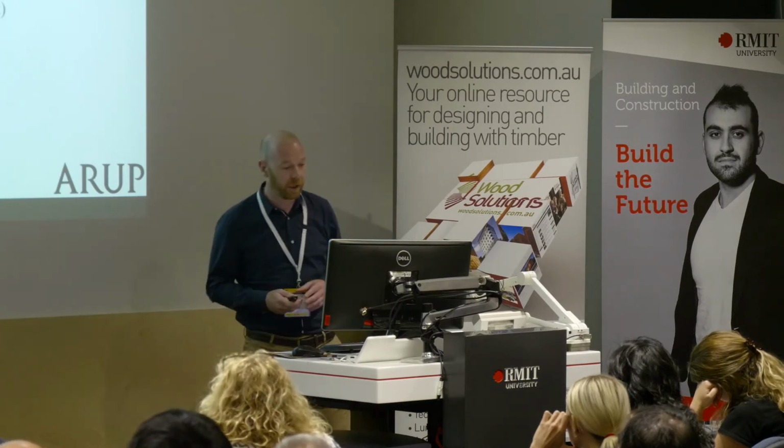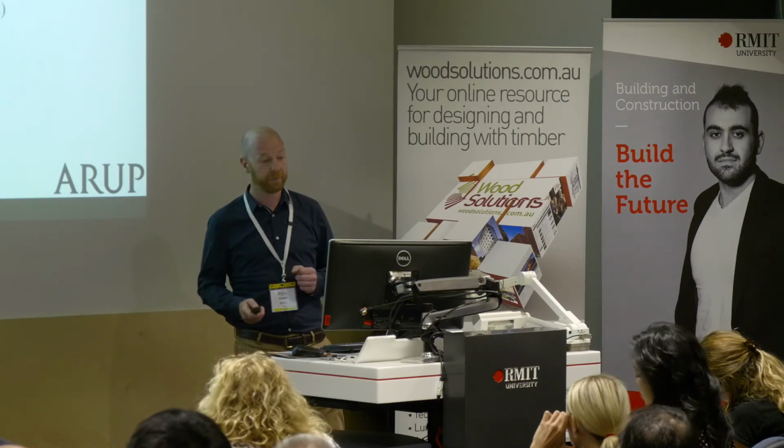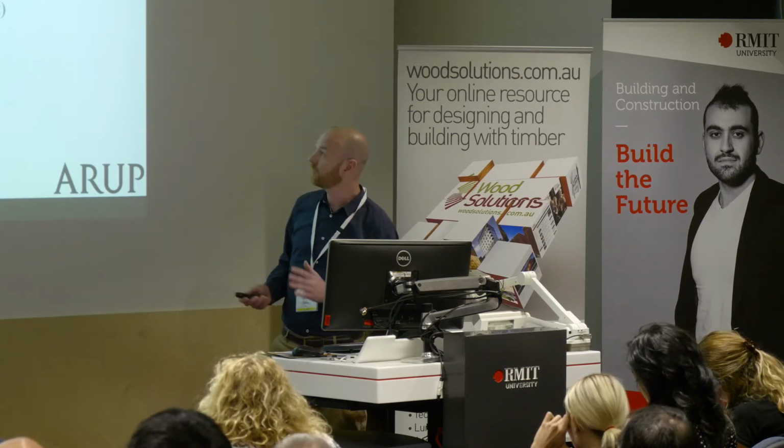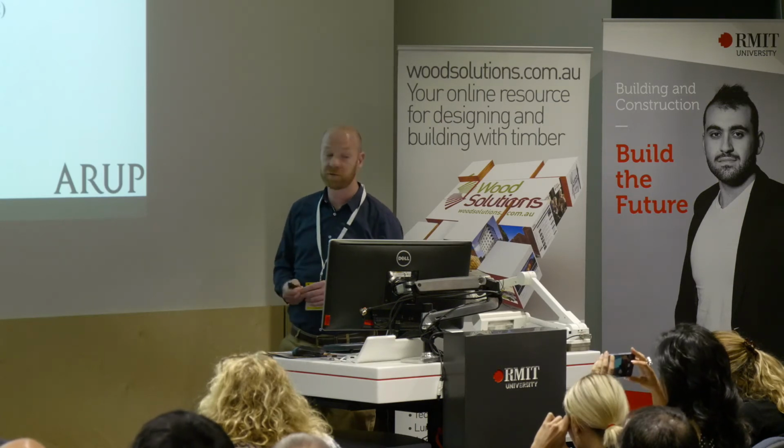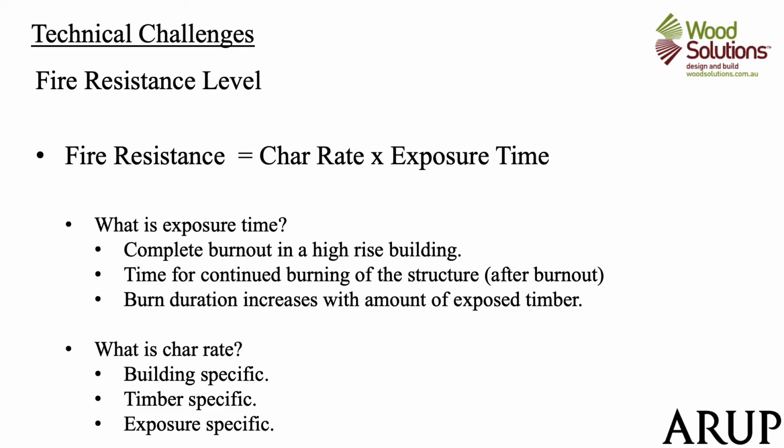In terms of structural engineering for timber buildings, fire resistance, very simple concept. Char rate times exposure time. But as Paul's touched on, it's quite complex in practice. So what is the exposure time? Again, it's going to be building specific. For a tall building, the complete burnout of the building, including the time for the structure to burn as well, if there's any exposed. And burn duration increases with the amount of exposed timber, as we've seen.